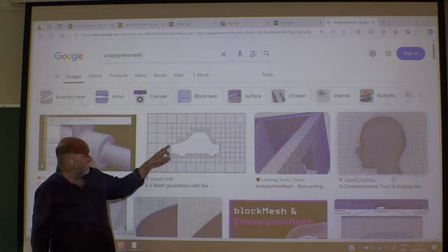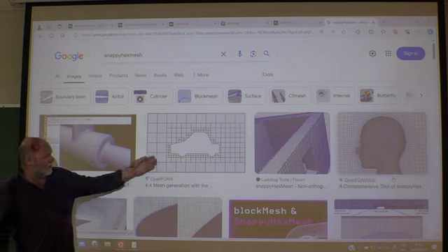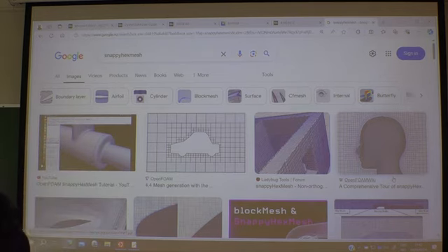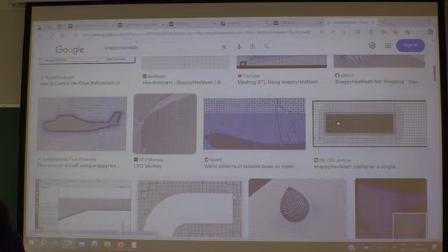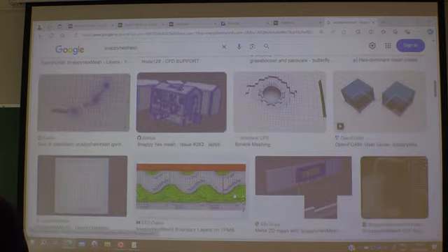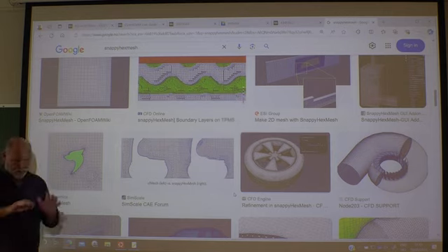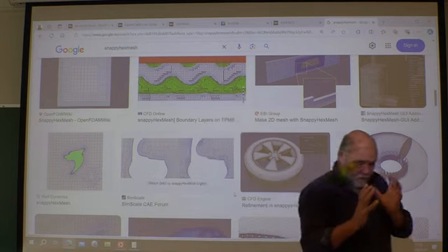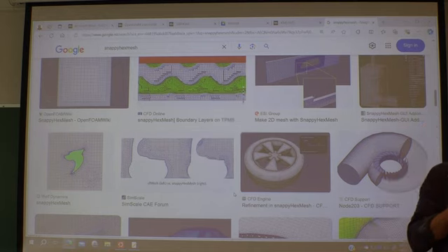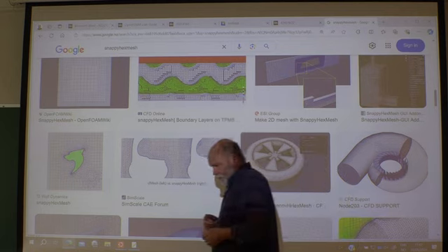We might have some curved surfaces on the interface in the end. This one is actually inside the user guide, if I recall correctly. We can have a look at it afterwards. So you have plenty of examples of how to use the snappyHexMesh idea. The point is, you use a uniform mesh initially from blockMesh, and then, given the geometry, tell it to resolve close to the boundaries better and better until you are satisfied that you really resolve complex geometries nicely.